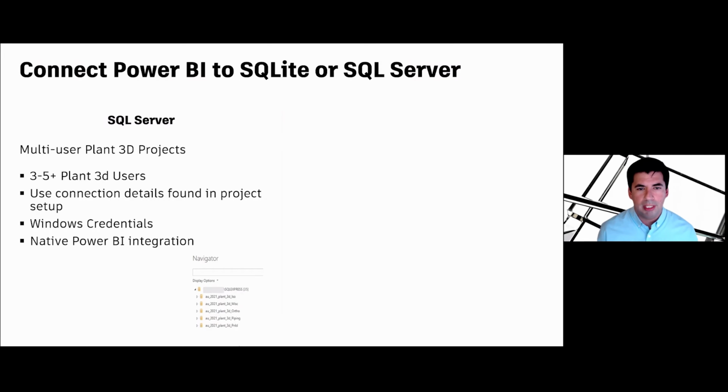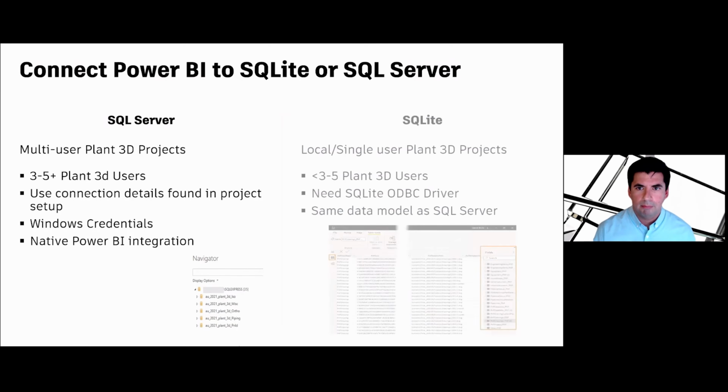If you're looking for the database or the server name that you should use, you can find that information in Plant 3D in the Project Setup window. The SQL Server connection inside of Power BI is native, so you don't need any extra tools in order to connect.